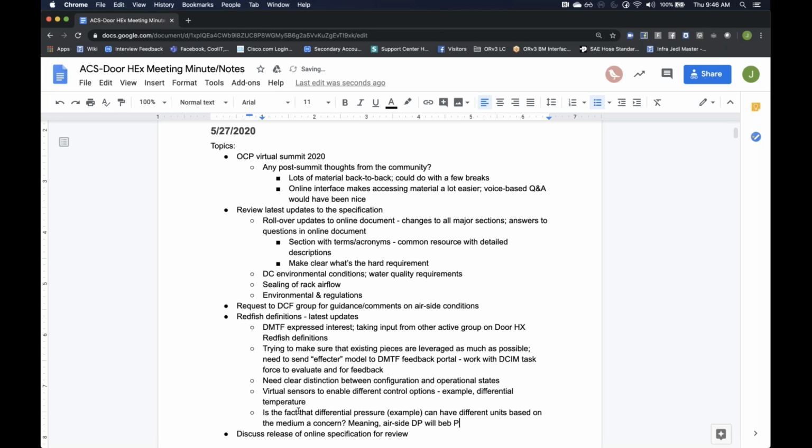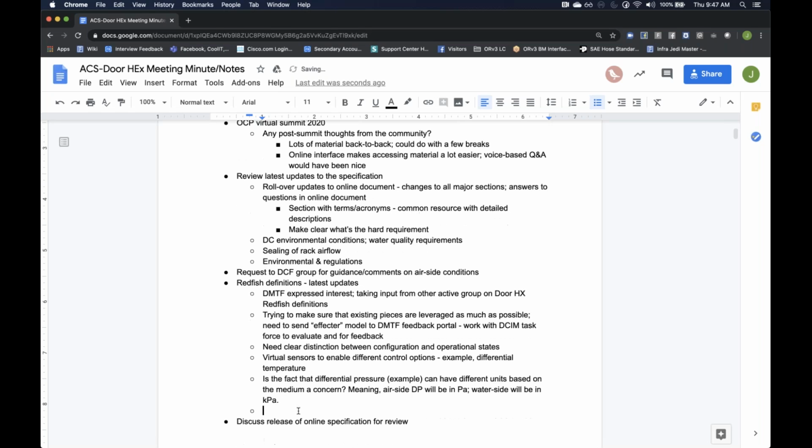Back to that configuration mode, if you go set up a door switch, then there'll be some property in the unit that will have a door status of open or closed, or something like that. So it would surface those as defined features, not as dry contact number 2 is open or closed. That's a different approach than folks are used to.